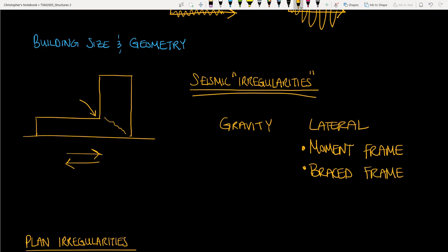And finally, we have a shear wall. These are the three main types of systems structural engineers design to resist lateral loads, and the placement of these elements in the building is key to the behavior and performance of the building, as we will soon see.